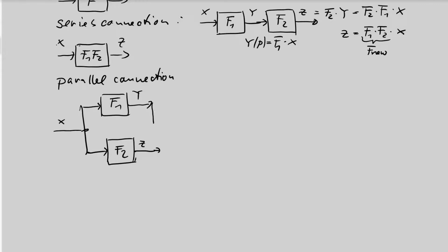So the only possible connection in a signal block diagram is that the outputs are combined together with a summing point. The summing point gives the output, say A, and you can directly calculate A is Y plus Z. Of course, a minus sign is allowed.